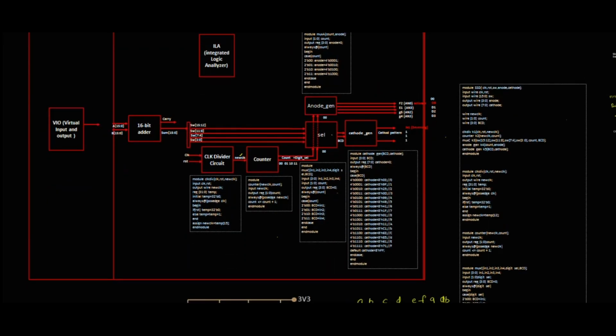This is the RTL block where I wanted to implement the 16-bit adder, and I will be generating a sum of 16-bit. So I will be loading the 16-bit into 4-bit sizes. This is the first 4-bit, and this is the second 4-bit, and third and fourth. This is how I will be dividing the 16-bit output that we have into 4 sub-combinations, right? Each of those 4 sub-combinations is of size 4-bit, and I will be loading them into the module.